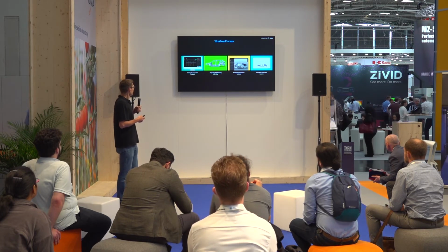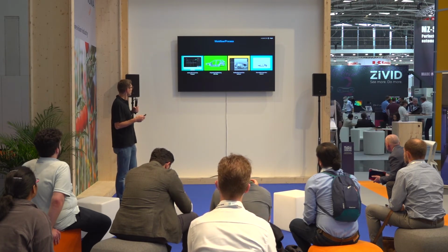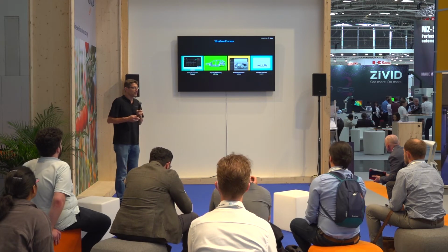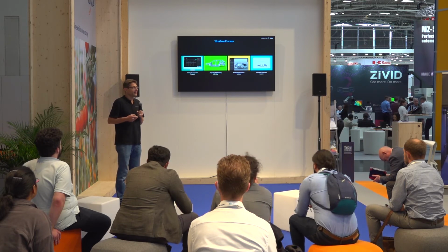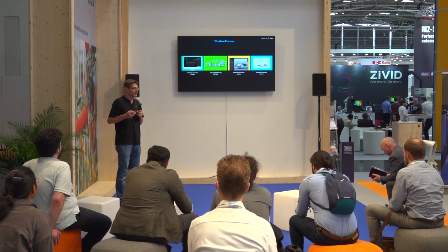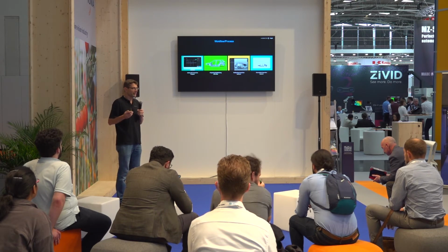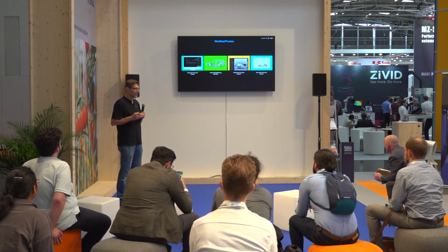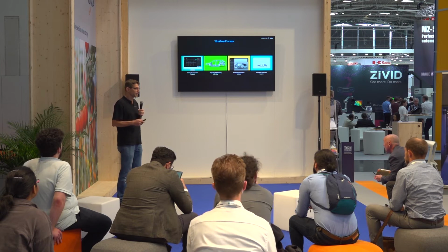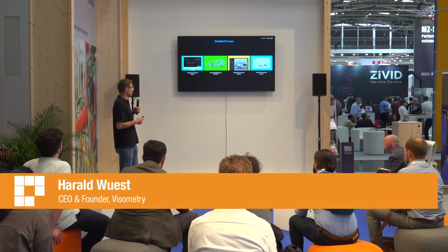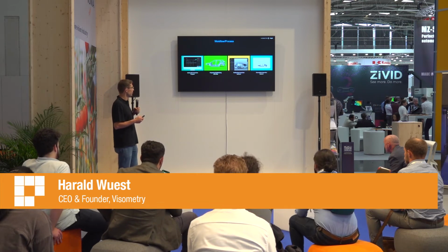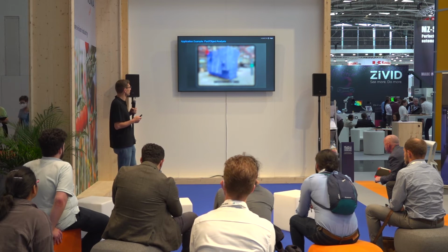At the beginning, as I just mentioned, we have the setup process. Here we have a CAD optimization framework where we take the 3D CAD data and import this, and do some simplification with the CAD data so that it is possible to take even gigabyte-sized 3D data. This will be reduced into a format so that only visible parts will be exported to the iOS device. Then on the iOS device, the inspection task can be carried out, and as a result we get the inspection report.